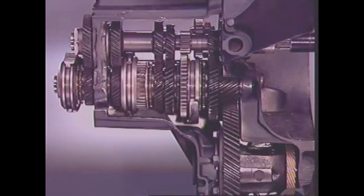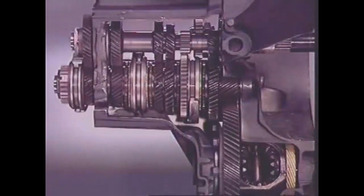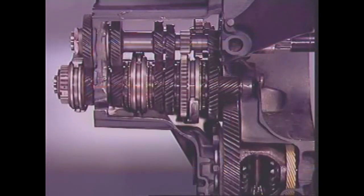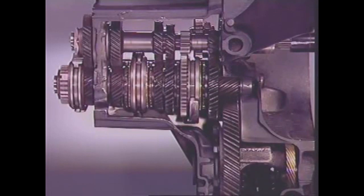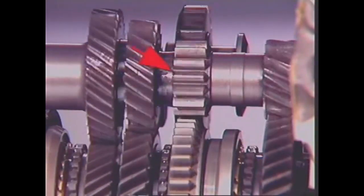The drive transfer is similar for fourth gear. The fifth gear ratio is provided by transferring the drive through the fixed fifth gear on the primary shaft to the engaged fifth gear on the secondary shaft. This is often an overdrive ratio, with the driving gear larger than the driven gear, making the driven gear rotate at a higher speed. For reverse, the reverse idler moves to mesh with a reverse gear on the primary shaft and the matching gear teeth on the outside of the first and second gear engagement sleeve.